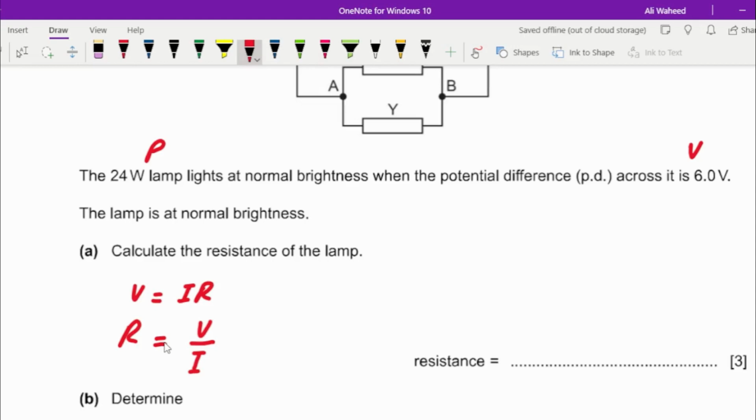Now there are different ways that you can do this question. One of the ways is that you straight away apply the formula of electrical power. So we have three formulas. P equals VI. Then we have P equals I square R. Then you have another one, power equals V square over R. Out of these three formulas, we think that the last one should be the most compatible one. The other ones can also be used, but then you'll need to find the missing thing. So we gotta use the last one. This would be the smartest pick.